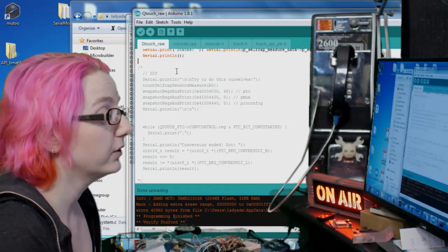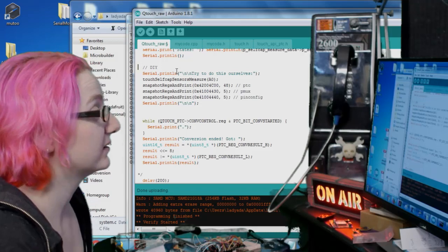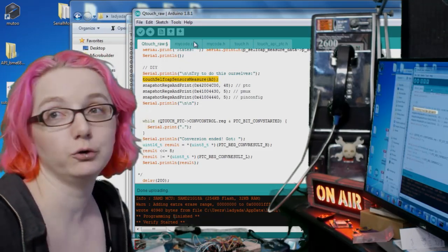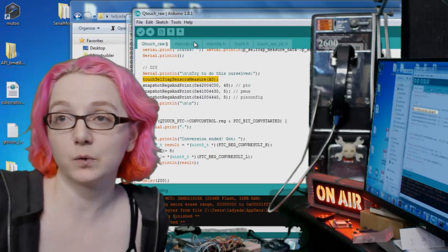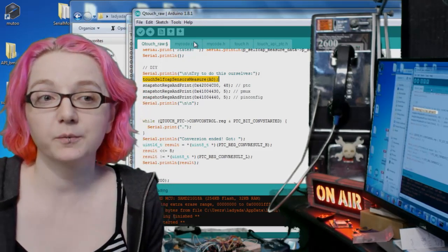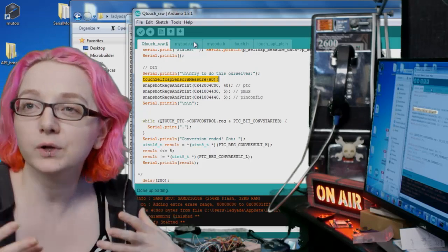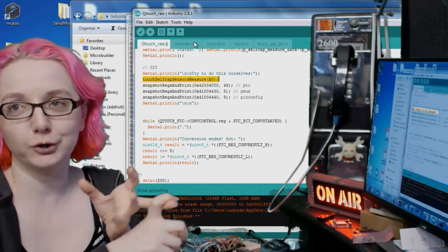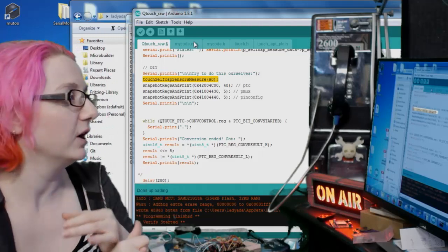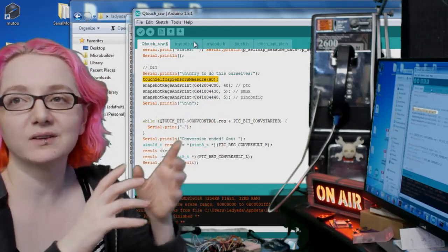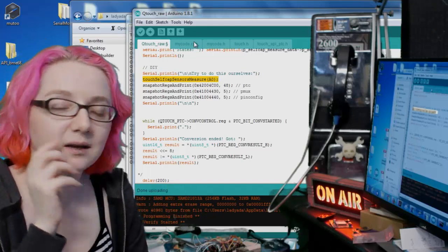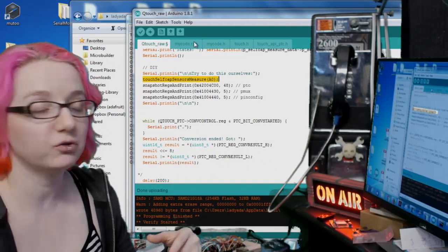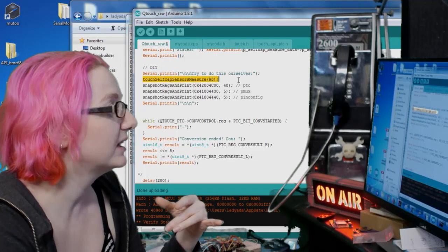So the code I wrote is really basic to start. Instead of using interrupts, I actually don't use them at all because interrupts just make things more complicated and make it harder for me to know. You can always add interrupts later. Again, you can always tune the resistor, tune the capacitor, tune the power usage, make it do multiple reads at a time. Right now, I want to read 1 thing at once, and then I'll just poll and wait for it to finish. So here's where I kick it off.